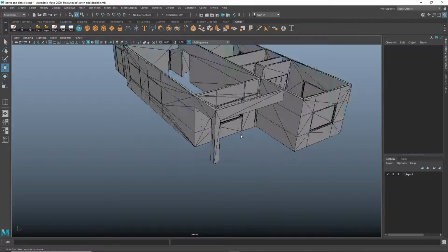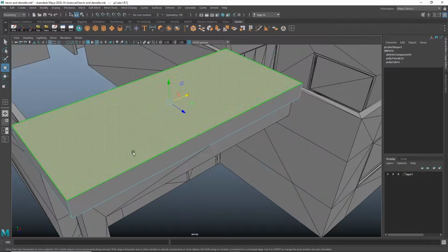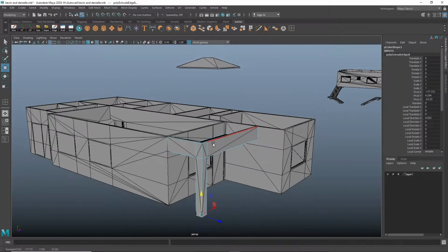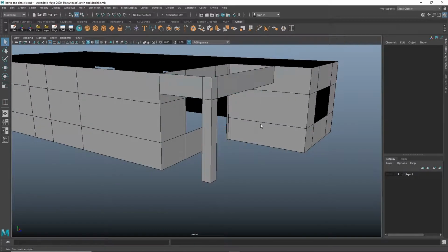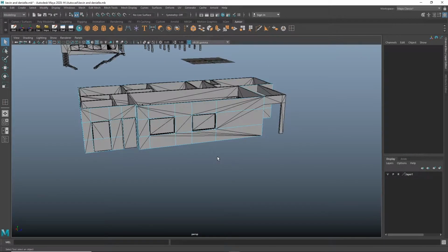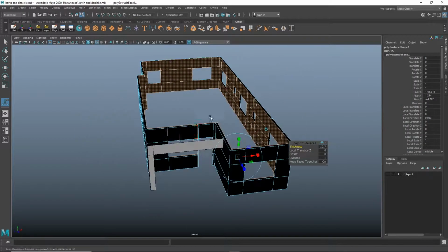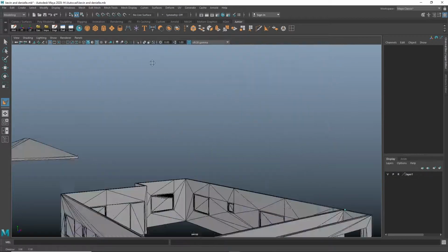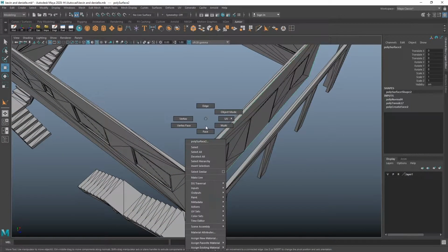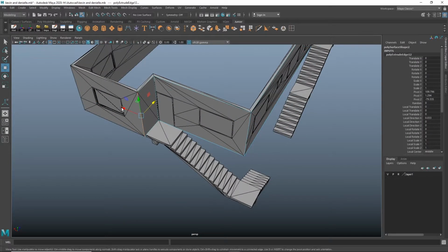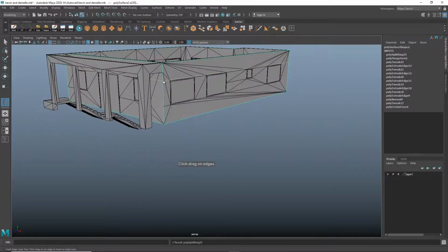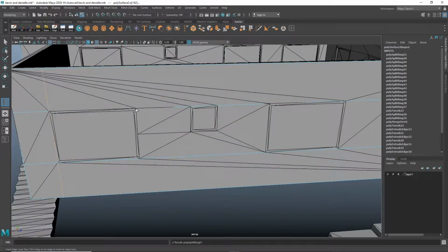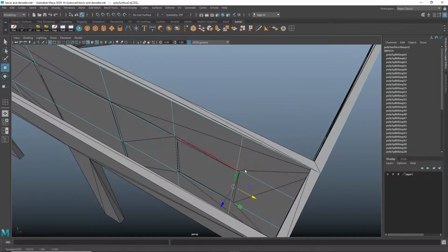So after putting it into Maya, I remodel all the topology, because if you look at the model that comes out of AutoCAD, you will see some strange lines running from the windows and the doors. It doesn't have clean geometry, and sometimes you would end up with problems when you go to render. You would find shadows coming up in the mesh itself, and that kind of spoils the look. So it's a lot easier to just redo the model.